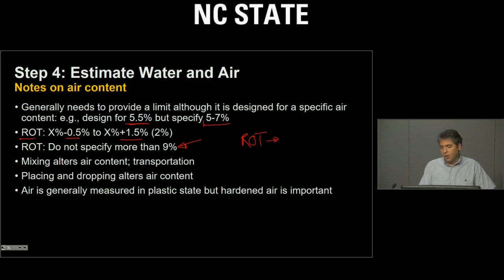For every 1% of air, the compressive strength f'c will decrease 5%. So this is very important. You do not want to specify a lot of air inside the concrete, because you will run into other issues, severely decreasing f'c of the concrete.